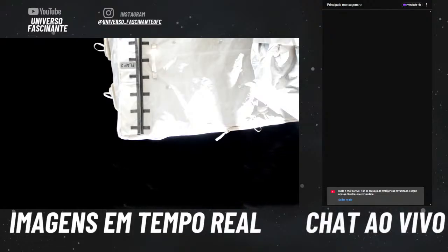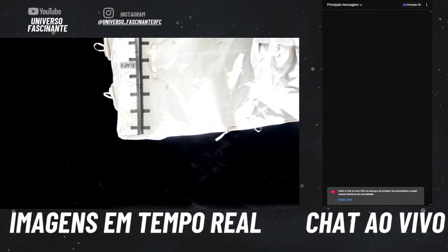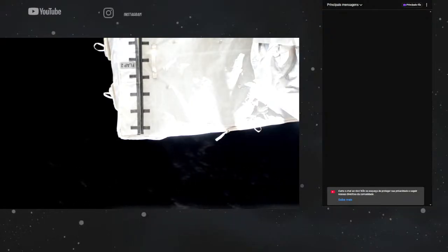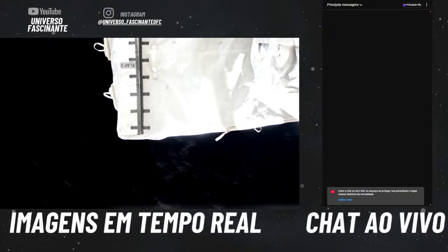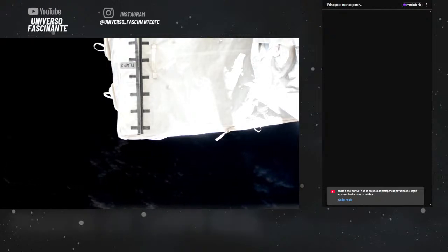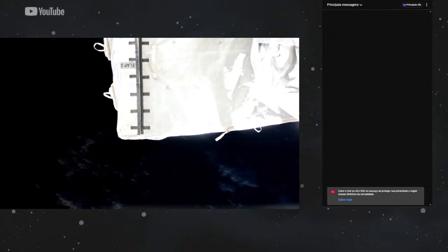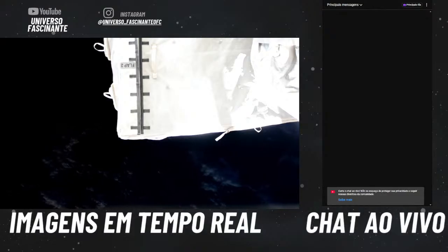Some 24 minutes after the deorbit burn, the pyrotechnics will be initiated to separate the 3 sections of the Soyuz spacecraft. The upper section, as you see in this diagram, is the orbital module. Right after the deorbit burn, that orbital module will be depressurized to vacuum in advance of the module separation itself.